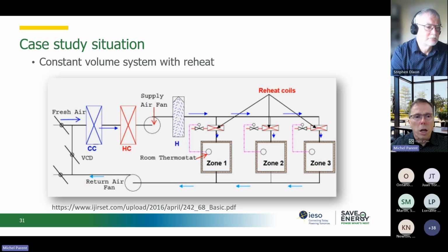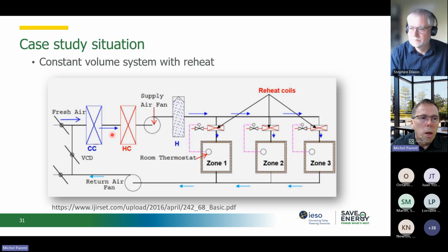Usually, if you've got a lot of zones with reheat coils, your heating and your cooling coil will be controlled by a duct sensor, which makes it a cold deck system. Now you could say, how am I going to define that? Just like a makeup air unit? And the answer is no, not at all, because this one, unlike the makeup air unit, has a recirculating damper.